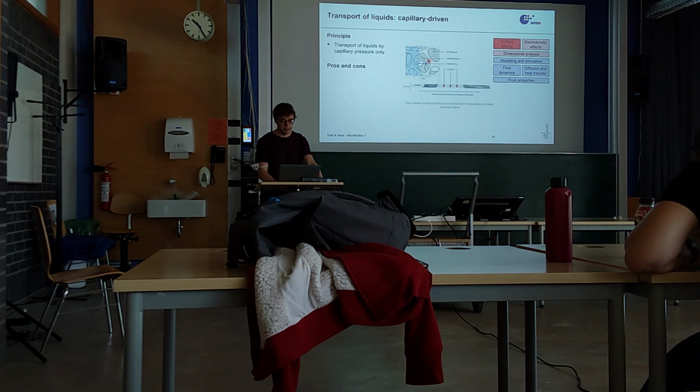using porous membranes. So within these membranes you have very tiny holes, and as you remember, the smaller you get, the bigger the capillary force gets, because we had this term 1 divided by the dimension, which is proportional to the capillary force. And this is why those small holes lead to quite big capillary forces, and that is often, not always, but often used for capillary-driven microfluidics.